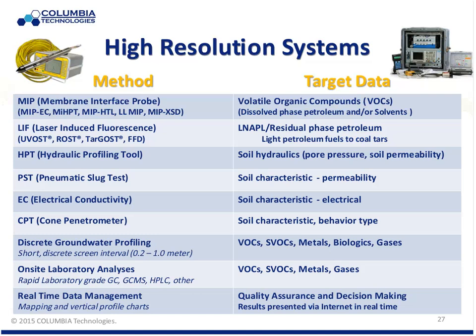The key here is you must have the residual petroleum present. So you think about it like a light switch. If it goes down and hits petroleum, it turns on. If there's no free-phase petroleum or residual-phase petroleum, you will not get a signal out of that. Excellent for tracking LNAPL spills.